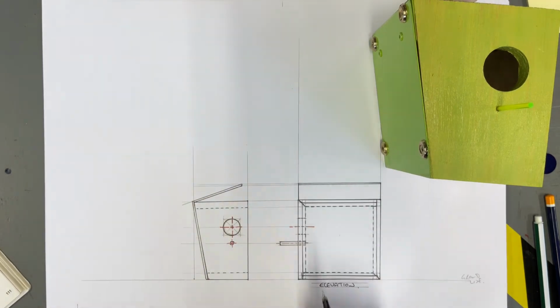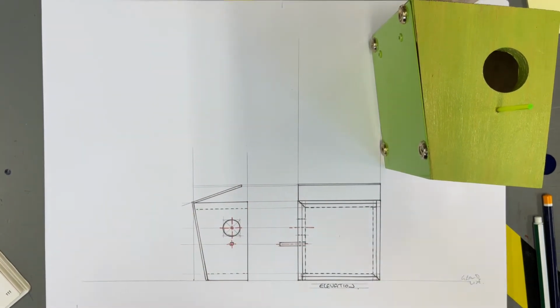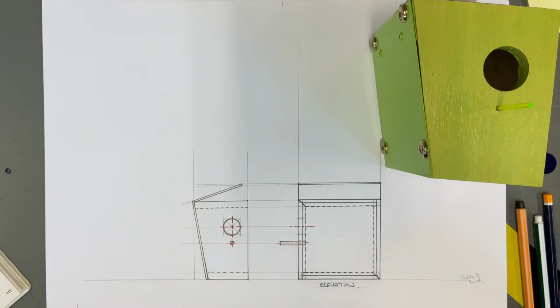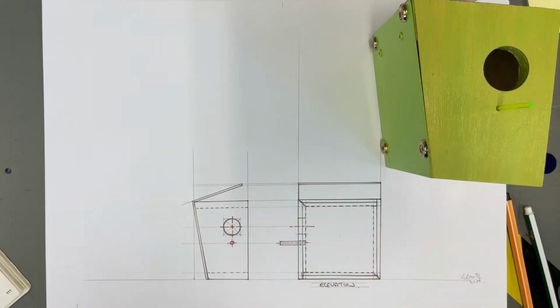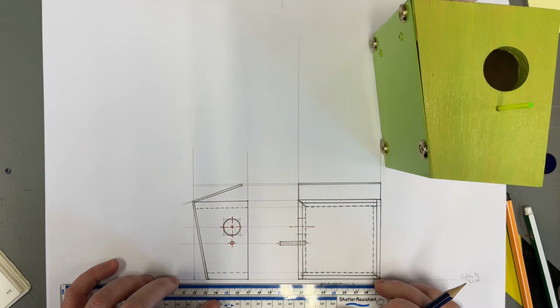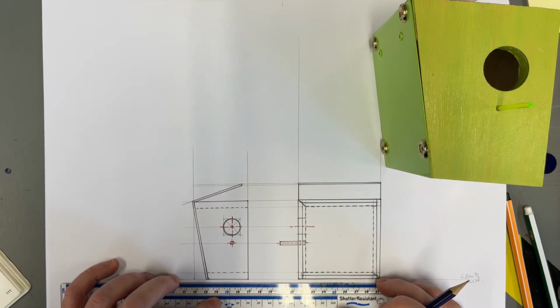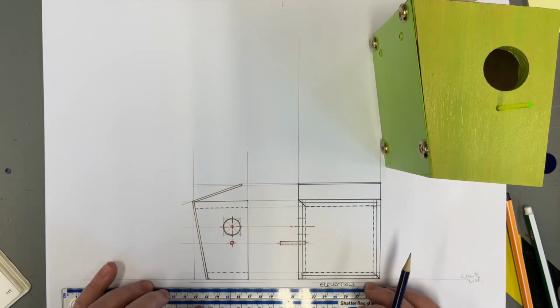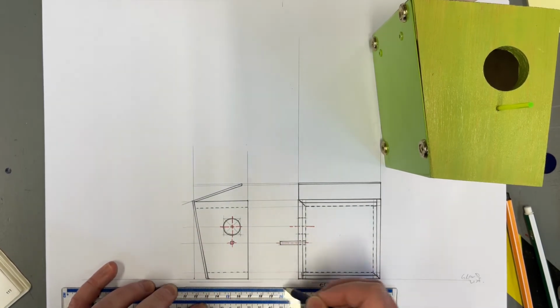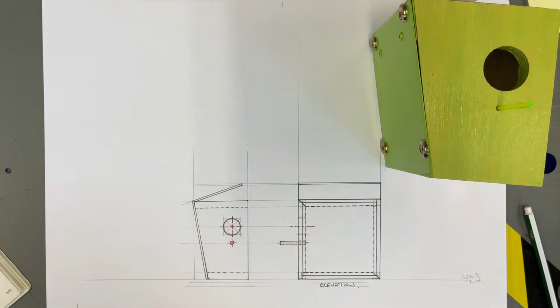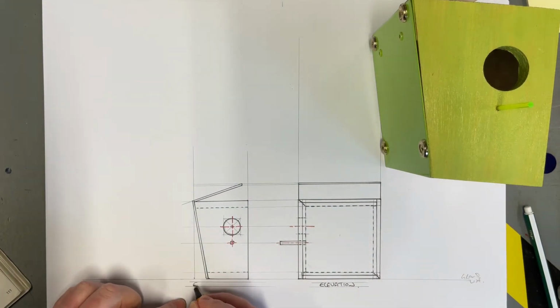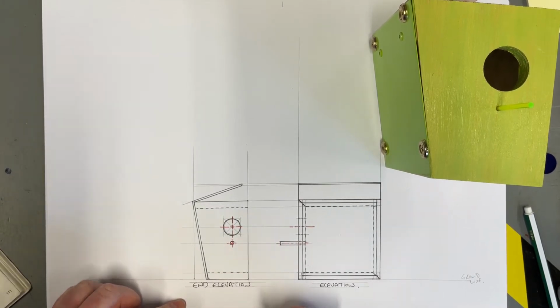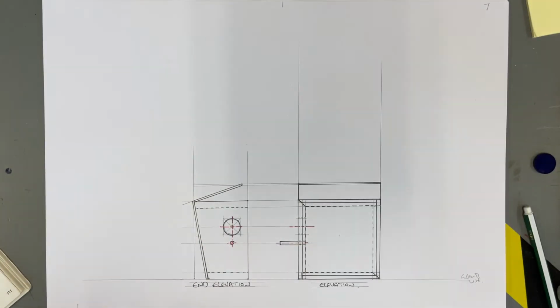And that would be good enough. Now we'll leave dimensions off for now, we'll cover those in a little bit. But again, underneath the view, I'm going to have a couple of construction lines to help put the view title in. I try to keep these in line with the elevation there. Super light. And then in capital letters, centered across the view, end elevation.